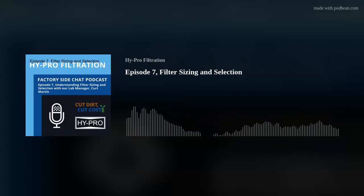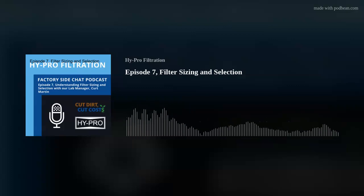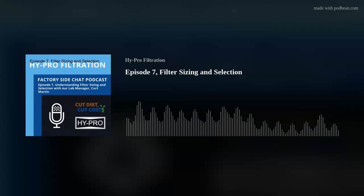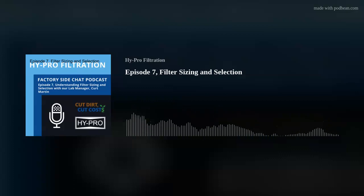One of the things I like to mention to the customer is if there's an error made where you're mixing those, one of them is not catastrophic, the other one is. So if we accidentally put a high collapse filter element in a housing that has a bypass valve, the negative is just spending too much money. On the flip side, what happens if we accidentally put a standard collapse filter element in a housing that has no bypass valve? Most likely the element's going to come out looking like a soda bottle that someone stepped on.